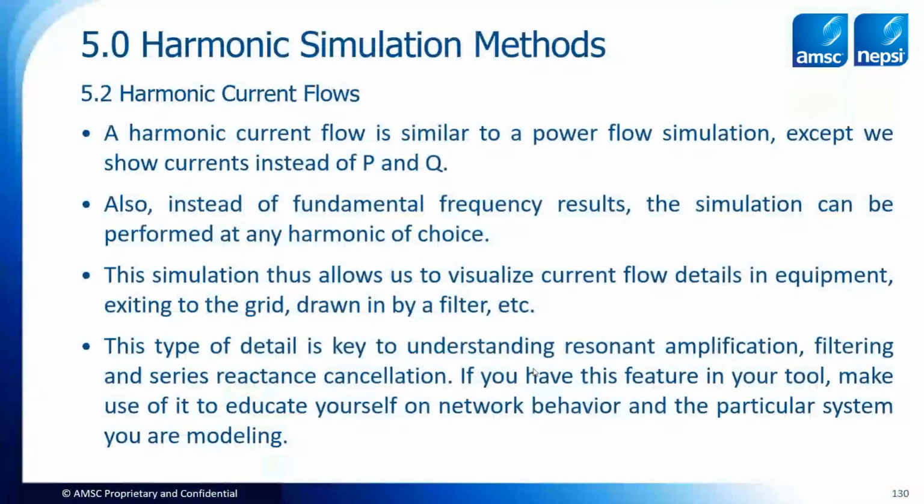Current flows are similar. We're going to the next simulation technique, which is called a harmonic current flow. And in this method, what we're going to do is treat it almost like a power flow, except we're going to show currents instead of P and Q. So we're going to pick a frequency. Now, you could choose fundamental again if you want to, but there's no reason to because we have a power flow answer. So typically we would choose a harmonic, something like the 5th or the 7th or some harmonic where we think there's a problem.